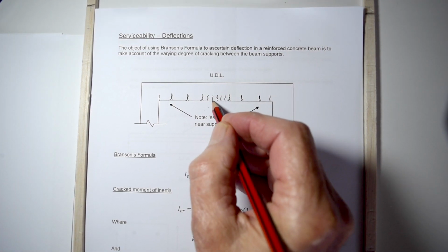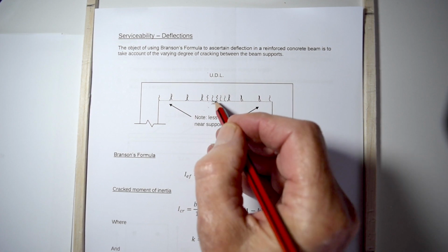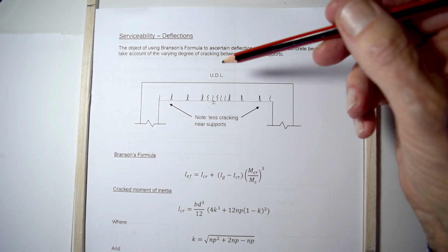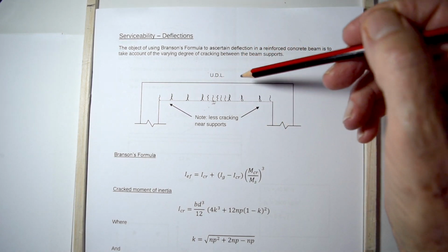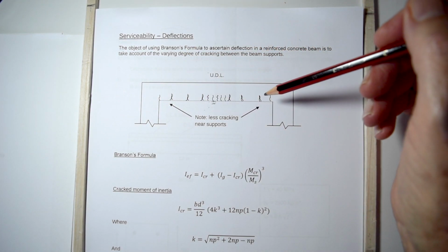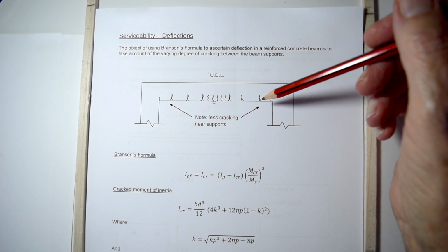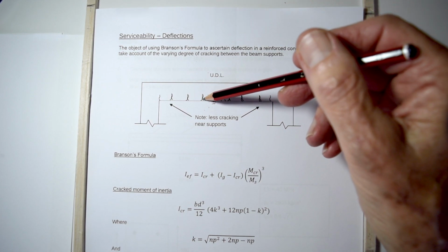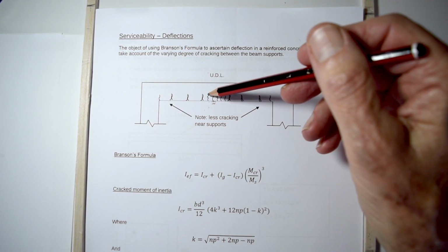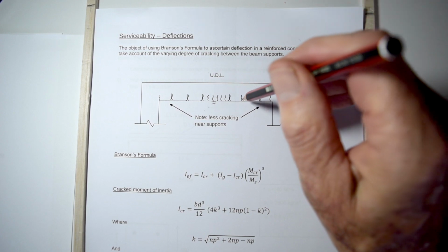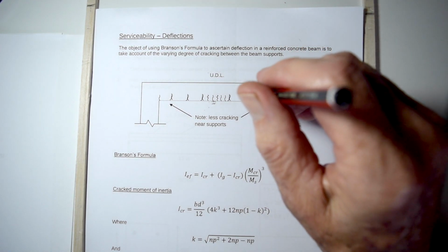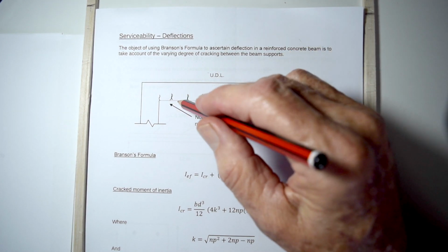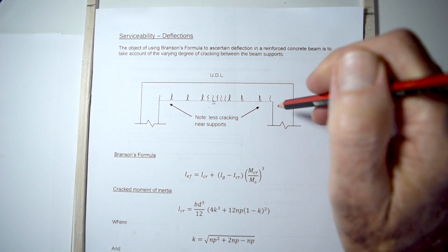That dimension there, as you all know by now, is the deflection. So it can deflect under its own weight, and it can deflect, obviously, when you put live load and additional dead loads on top of it. Many laboratory tests have shown that the cracking near the center of the section, where the deflection is the greatest, is greater than the cracks as you approach the supports, and that's why this drawing illustrates that.